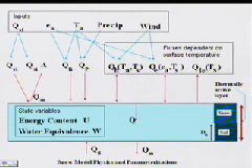translate water molecules from solid phase to gas phase, is a function of the vapor pressure in the air, how dry the air is, as well as the temperature at the surface, because the temperature at the surface controls what the vapor pressure is at the surface. And then there's an outgoing long-wave radiation, which is only a function of the temperature at the surface. Then all of those fluxes had better balance with the flux into the snow by basic conservation of energy.